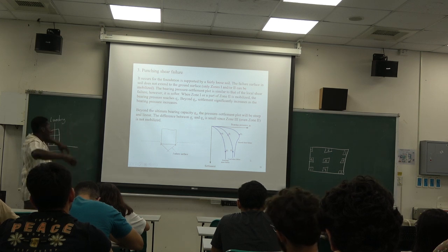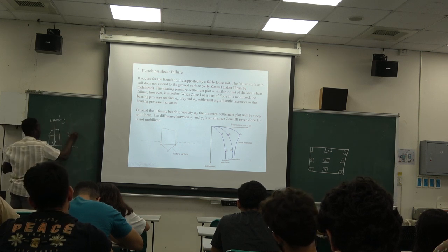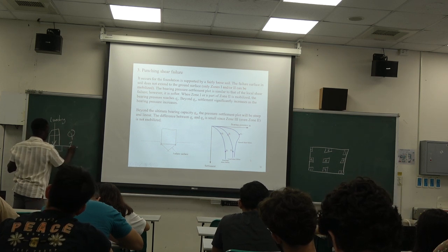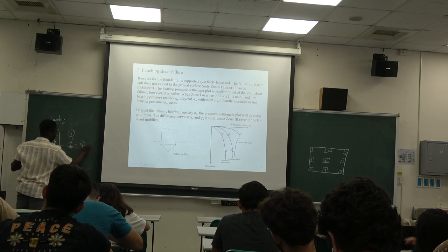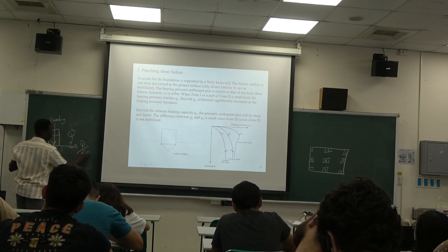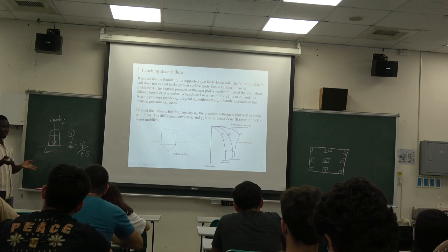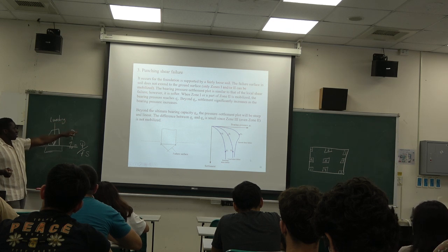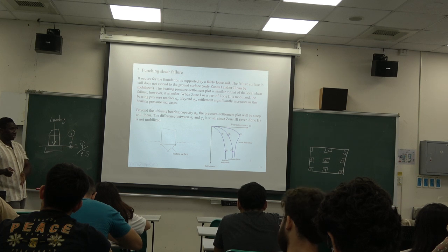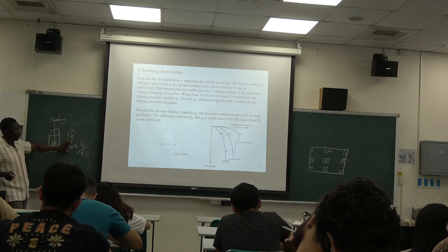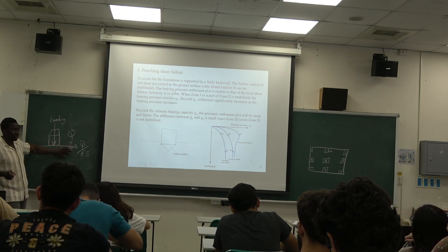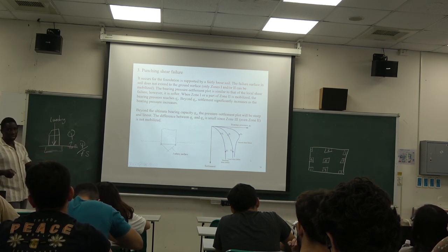So that's why whenever we do design, instead of using that actual Q, we will use what? Q allowable, and then you have Q divided by the factor of safety, just to be safe. Because if you reach that ultimate point, there's no going back. It's just your structure is going to fail. So that's why we usually rely on the QA, the allowable component, so that even if we reach this point, our structure might still be safe.